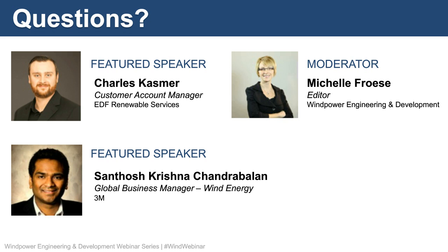Next, I have a question about retrofits. Is the cost of retrofitting significantly less if the blade is already on the ground? Robert mentions that they're doing a gearbox change out and they have that scheduled, and we're considering adding VGs at that time. Does that make sense to do it that way? Yes, when you're installing VGs on the ground, you are going to have some reduced cost. The labor is going to be much less because you're not climbing the turbine. Also, you're not going to have the downtime because you're already taking the turbine down for a different repair. So you're maximizing your downtime.